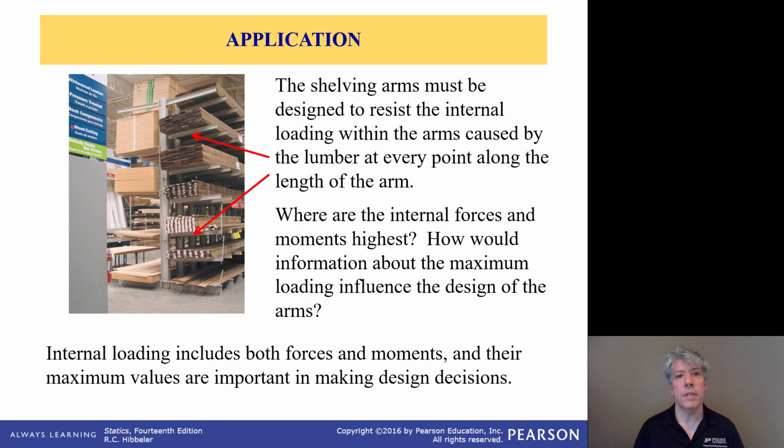It's not enough to calculate the loads, the internal loads in the material at one point. No, we need to calculate the loads along the entire length of the beam to determine where the loads are largest, and from that decide whether or not a given cross-section is adequate in order to support the load.